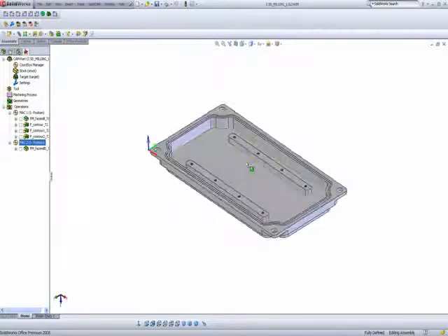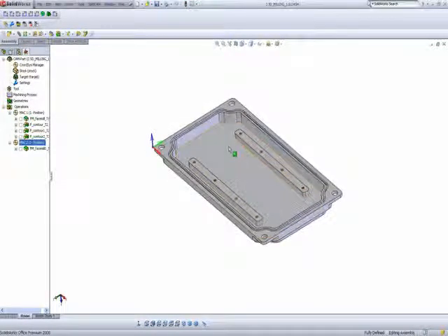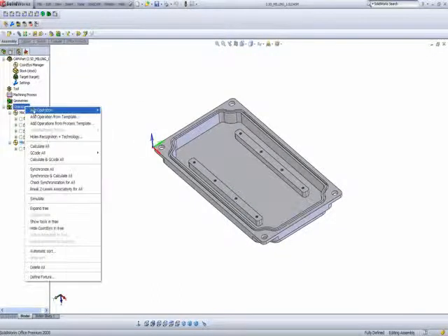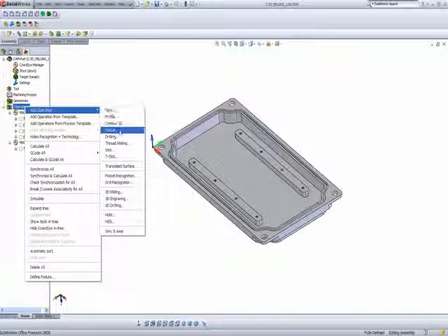So what I'd like to do in this particular part is first mill out a pocket from the upper level over here up until the depth, the height of this particular island, and then do another pocket operation from this height over here of the island all the way down to the floor, and then including the operation of the islands. I'll start my operation by adding operation of pocket.